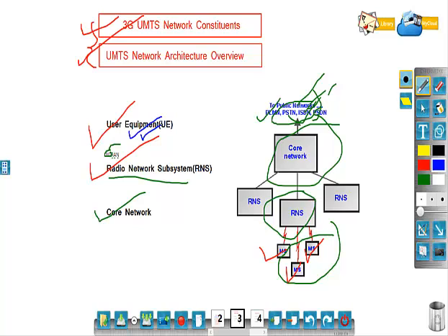There are a number of elements within the UE that can be considered separately. So we'll think about the RF circuitry, the processing, antenna, and battery. First we will cover the UE RF circuitry. The RF areas handle all elements of the signal, both for the receiver and for the transmitter. One of the major challenges of the RF power amplifier was to reduce power consumption. The form of modulation used for WCDMA requires the use of a linear amplifier. This inherently takes more current than the nonlinear amplifiers which can be used for the form of modulation used in GSM.